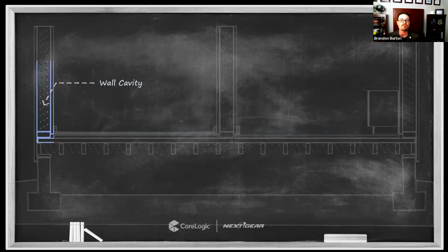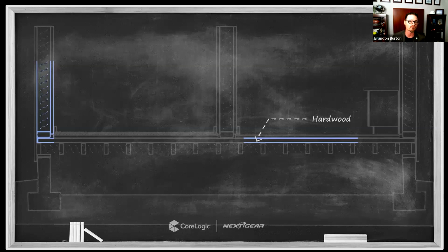Understanding when these systems are necessary means that we need to, again, understand what are we dealing with for affected surfaces? Where is the water evaporating? Right? And is that water evaporating in hidden, trapped, or otherwise covered areas or spaces throughout the project? For example, is the water evaporating from the back side of a multi-layer wall assembly or from the wall plate inside the assembly because we had standing water or water running down through the wall cavity itself? Or is the water evaporating in the decking material beneath the hardwood floor? Right, trapped underneath the hardwood itself? Or is the water evaporating behind or underneath a set of cabinets?